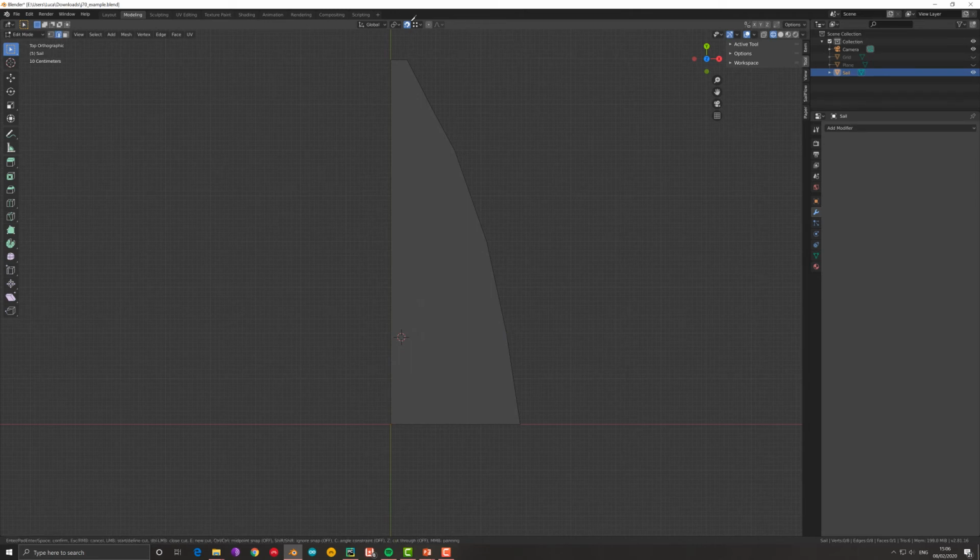To help the knife tool to work, I suggest that you go to the top where there is this small magnet and you tell it that you want to stick to edges. So you press K to get the knife tool again, and you go to the first element where you want the crosscut to end, the radial to end and the crosscut to start. You press enter and you have it.